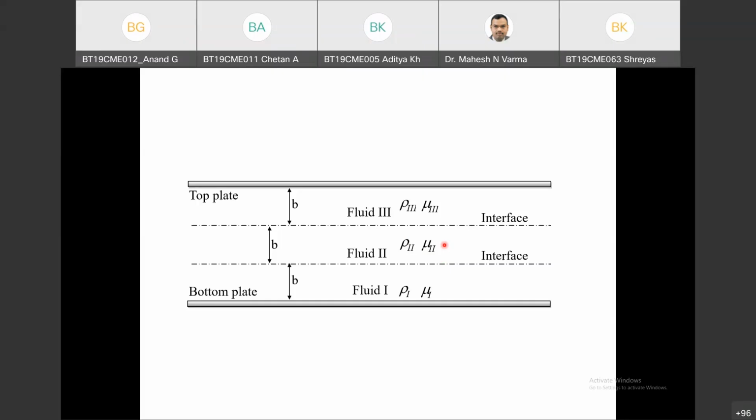So this was the input given in the previous problem. Which is the property based on which two materials are considered different phases in momentum transfer? It is viscosity. If two materials have the same viscosity, they are not different as far as momentum transfer is concerned. I'm not talking about thermodynamics, reaction engineering, mass transfer or heat transfer.